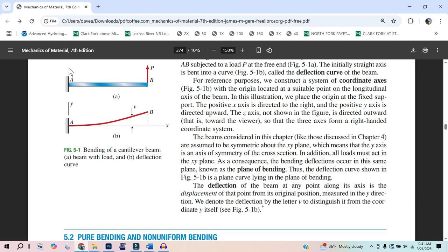All right, so now we can say, what moment did we put on it? This thing was going to spin this way. I had to put a moment this way. Back to our sign convention. If we draw this, a moment this way is going to be a smiley face, and it's very simple to do. If I have a moment curling this way, put the same thing on the other side, and yep, that's going to make a smiling face. That's going to be a positive moment.